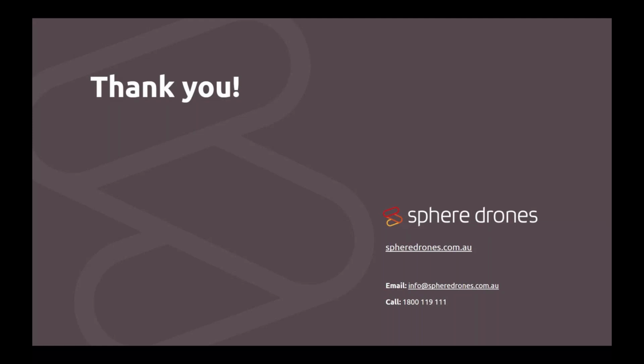Nikita, what kind of payload was used for the LiDAR case study? So in terms of the options that we support at the moment, obviously the L2 is DJI's latest solution. Really nice, integrated, streamlined workflow. The other option that I mentioned there, Nikita, was the YellowScan lineup. So the Surveyor Ultra is the flagship from YellowScan, really, really good vegetation penetration. That's the Surveyor Ultra that I was referring to there. So if you do have any further questions on that one, Nikita, feel free to reach out. We can have a look at your specific use case.